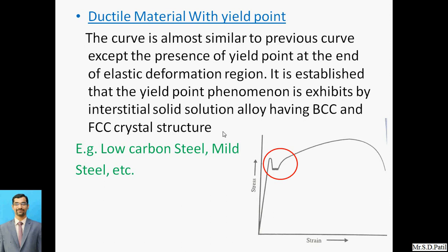The yield point is a phenomenon where, after the elastic deformation, the stress suddenly drops and strain hardening starts, and then the stress increases again after some near constant region. Here we can observe a drastic change in stress and strain. In this zone the stress has dropped, strain hardening has started, and the stress is almost constant. This is the phase change moment from the elastic to the plastic region, and we observe this in low carbon steel or mild steel.